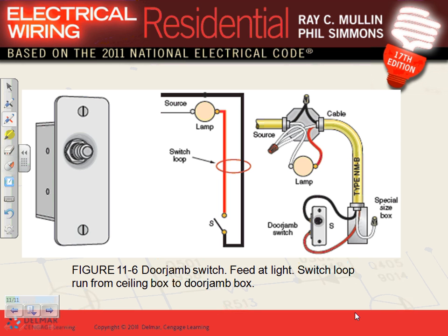So when the door jams on it, it opens it, so the light goes off. When the pressure goes off that jamb switch, the plunger will push the contacts to close, right? When you release the door, open the door, and the light will go on. So that would be a normally open, held closed contact. Normally open, held closed with the force of the door.